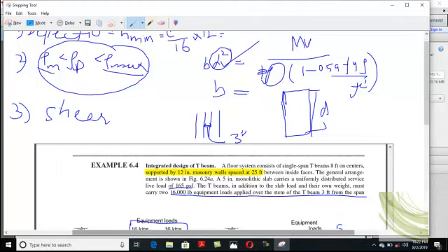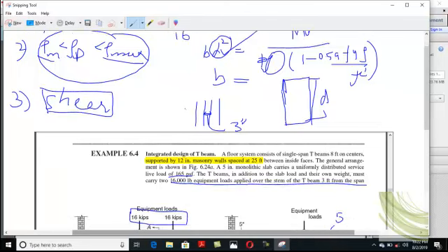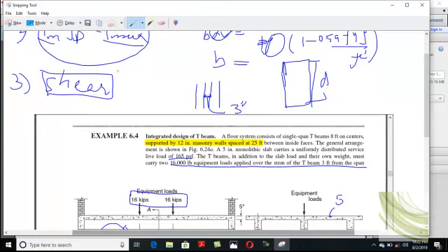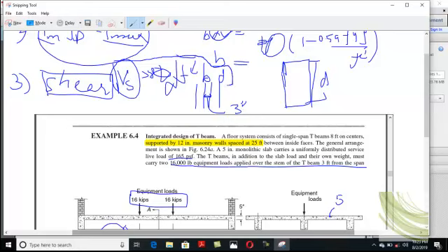Okay, so shear criteria must be fulfilled, because whenever we calculate the shear Vs, if it is greater than 8 phi into fc prime into bw into d, we need to revise our cross sectional dimension, because shear is so much high.